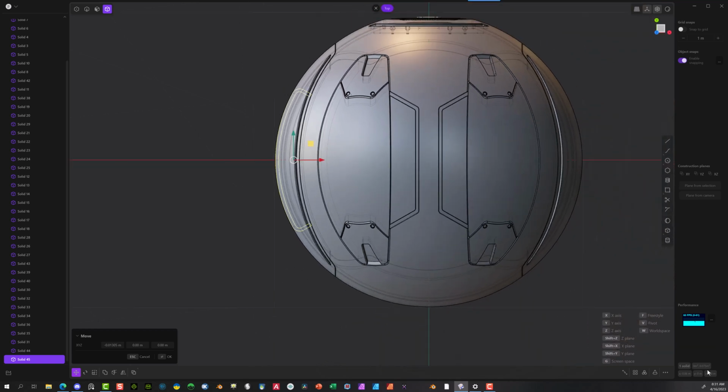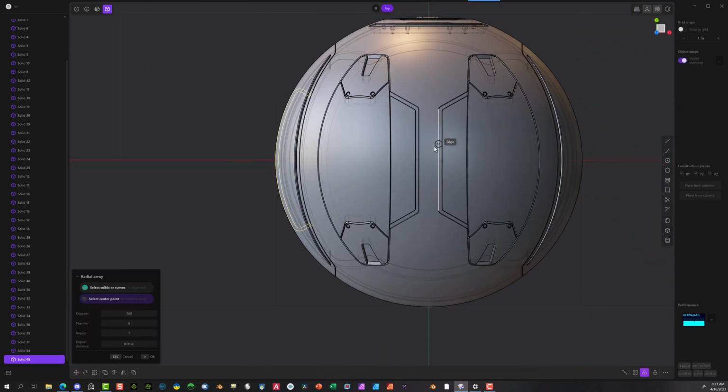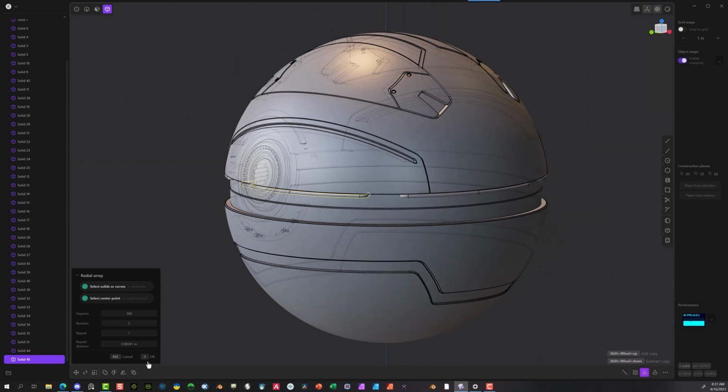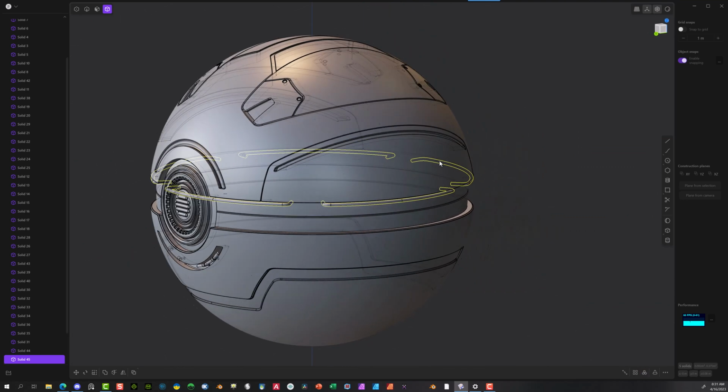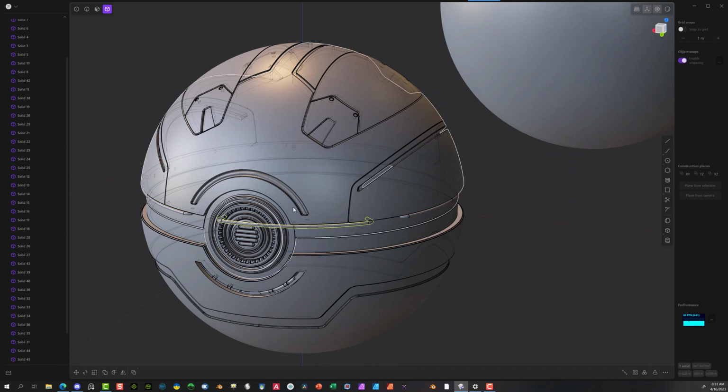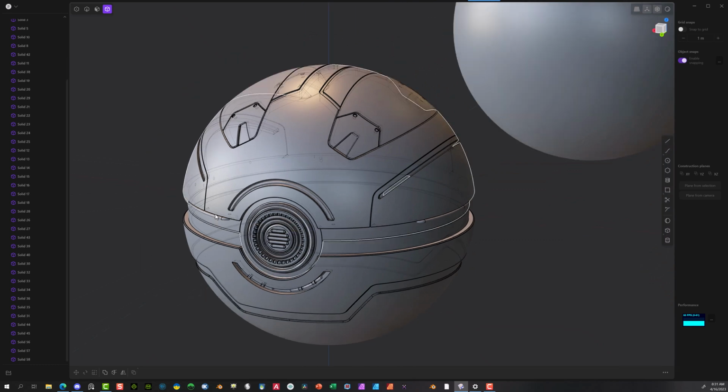And let's go ahead and hit the radial array. And we'll select the center. Now in this one, I'm going to go down to 5. And what that does, this goes all the way around. Say OK. There's one in the center here I'm going to get rid of, which is this one. Delete it. Hit the Shift key.